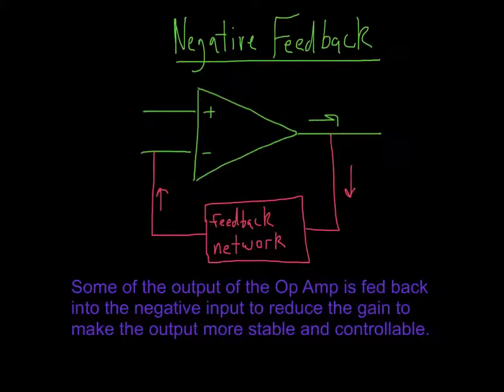So here's what's happening here. I haven't shown you an input yet, but you might be putting an input either on the positive or negative, or maybe even both. And if we didn't have this feedback loop here, what would happen? Vout would be huge, or it might hit a rail, like the 15 or the minus 15, or we'd have to make sure this difference is very small.